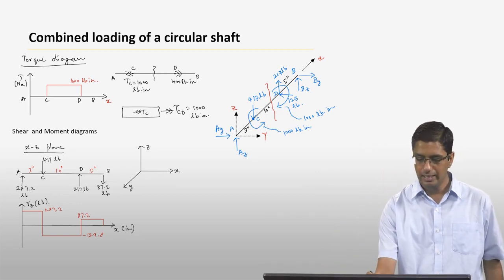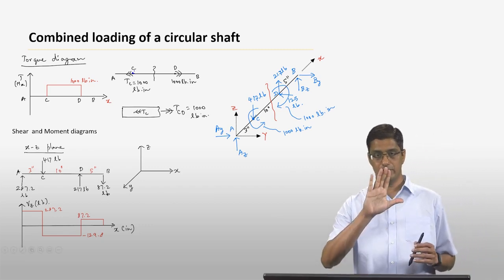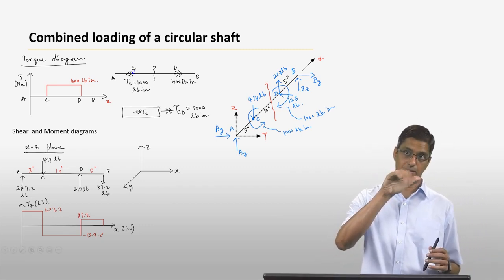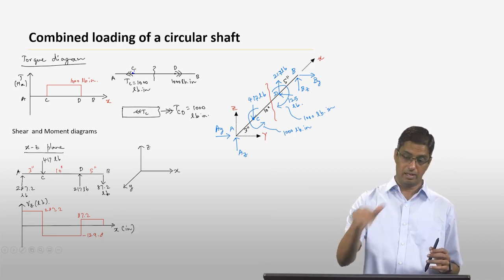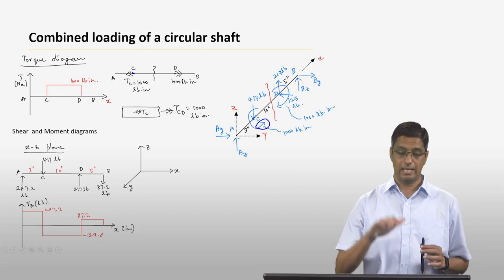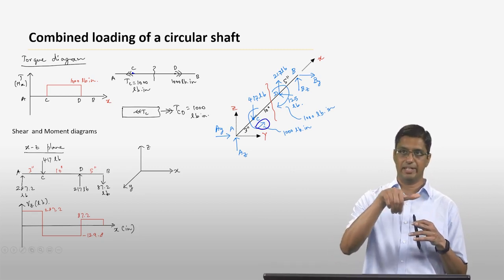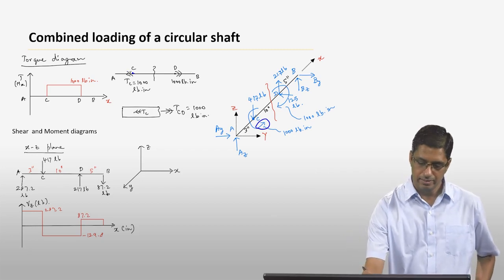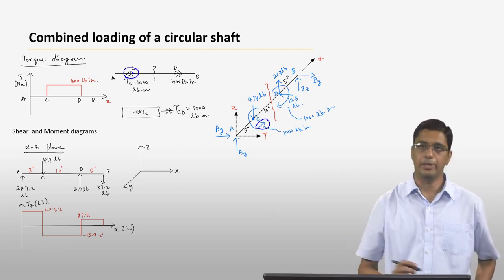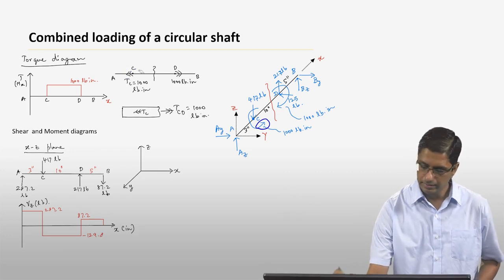If you look at this point C, you use your right hand rule. My fingers are curling along the direction of the torque there, and if I do that, you can see that my right thumb is pointing in the left direction. That is why the torque at point C is pointing to the left. So that is an external torque.